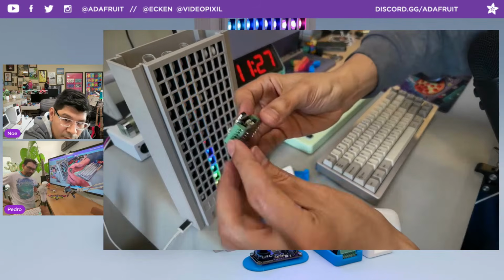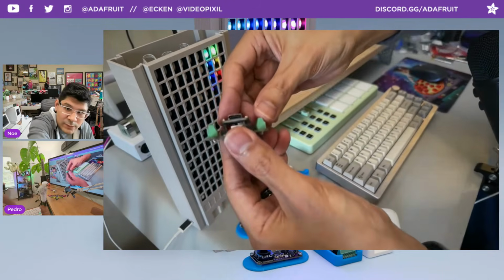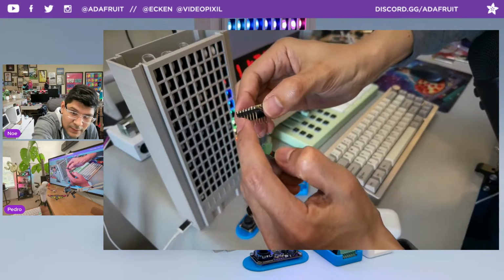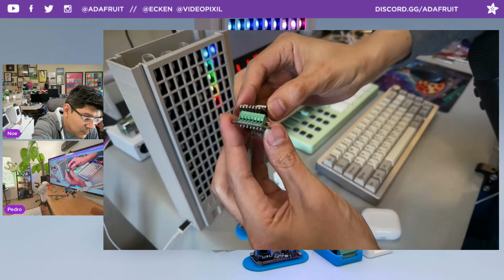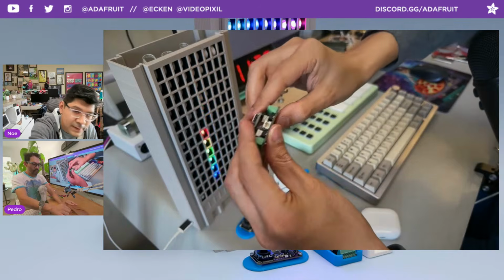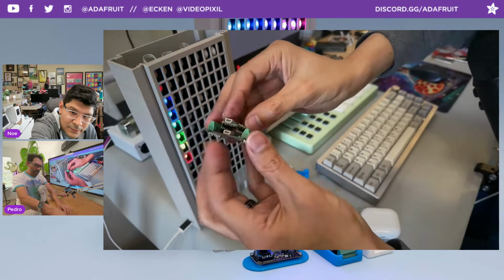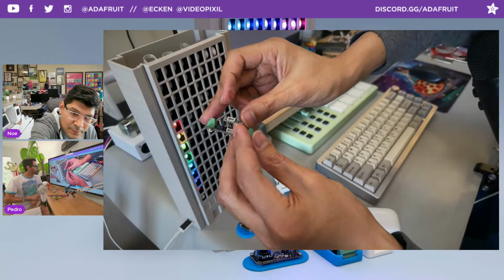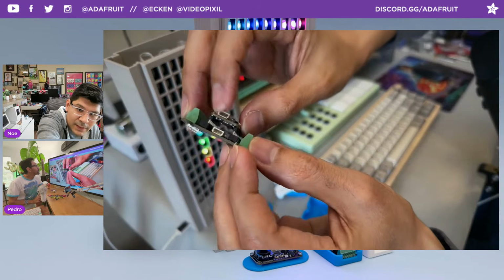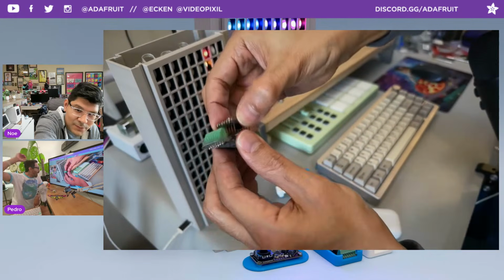Why is it so chonky? Well, it's because these screw block terminals are chonky. And this will only work with standard size headers. So if you have short male header pins on your QT Py, it won't line up. We're just hoping that folks know that. We'll write that in the copy too. But there's a good amount of clearance between the bottom of the QT Py and the top of the BFF terminal block.